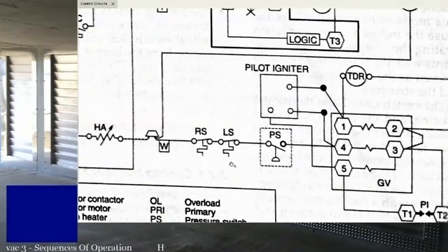Basically, those are both temperature activated switches. If either one of those is not closed, so the flame has rolled out at some point or something's overheated, then you'll never get power to the pressure switch either. But generally, you can check everything up to that pressure switch. You can check voltage right at the pressure switch to make sure you're getting it before but not after.